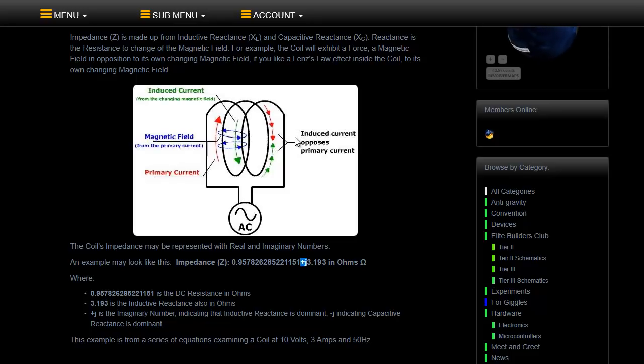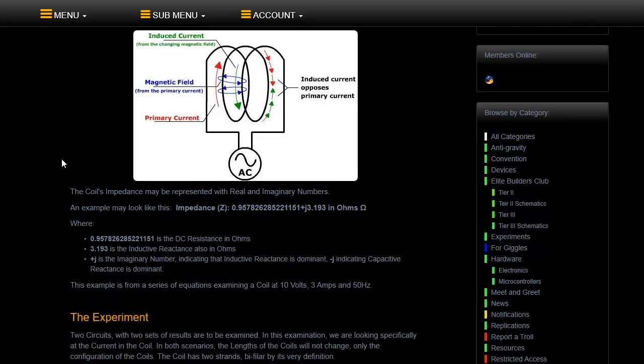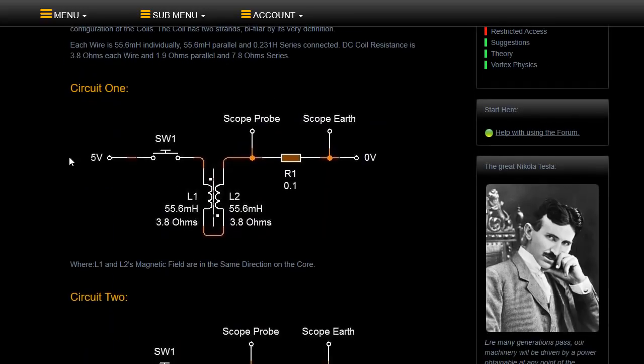So it's sort of in reverse. You've got to think reverse. The faster the motor's going, the lower the current it's going to draw from the source. And the slower the motor's going, the higher the current that's going to be drawn from the source. Okay, so it's the time rate of change of the magnetic field within the coil that creates the back EMF. It's reasonably well known about the motor scenario. Most people know about it, but no one really has investigated how to cancel it.